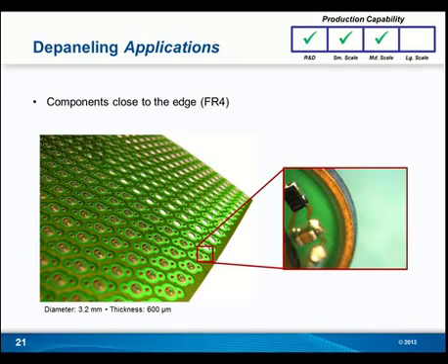Yes. Gotcha. Really the first thing that the laser does when you press start is it looks for the fiducials, reads the fiducials, and then it starts processing your board, whatever you need to do.